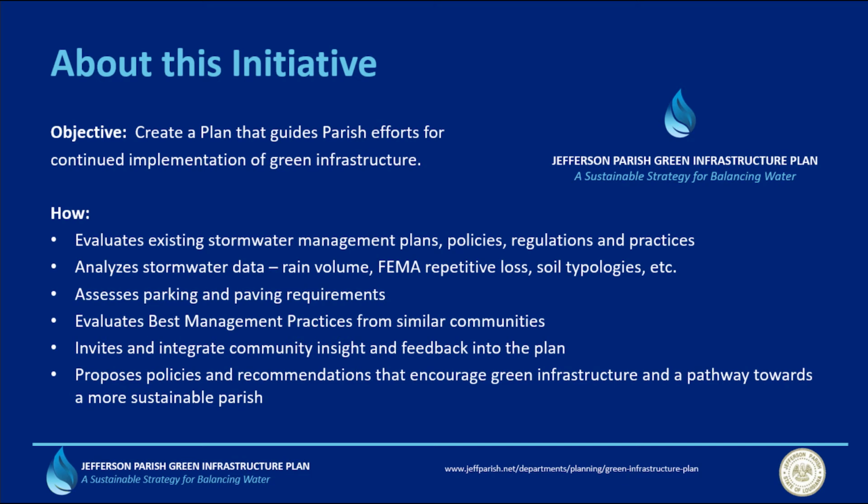We will analyze stormwater data, rain volume, FEMA repetitive loss, soil typologies, etc. Assess parking and paving requirements. Evaluate best management practices from similar communities. Invite and integrate community insight and feedback into the plan, and process policies and recommendations that encourage green infrastructure and a pathway towards a more sustainable parish.